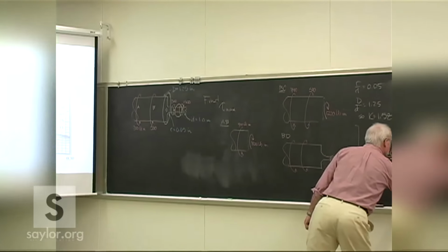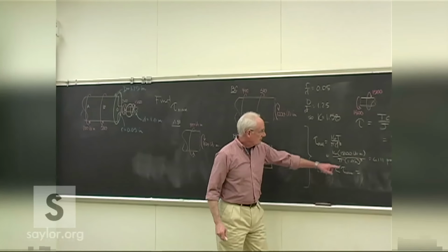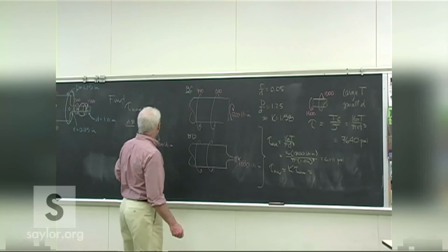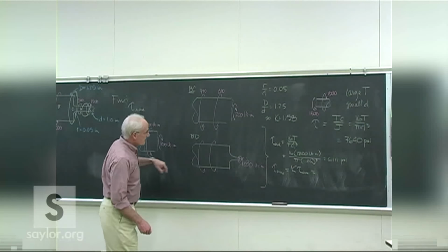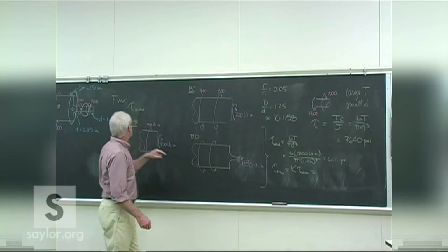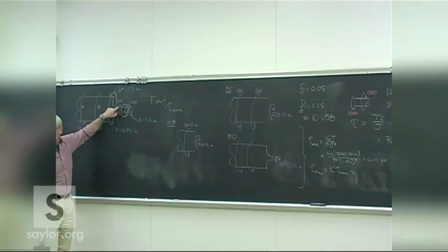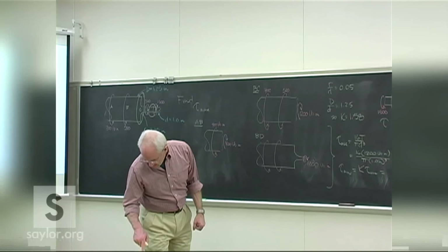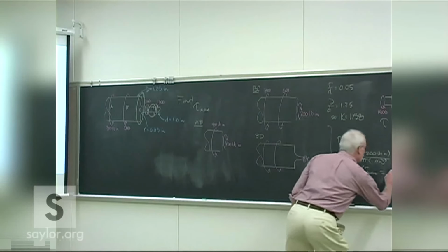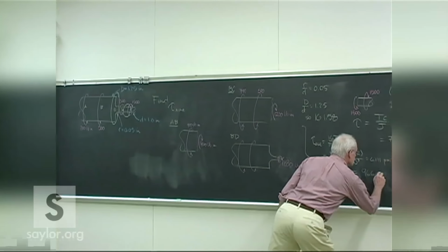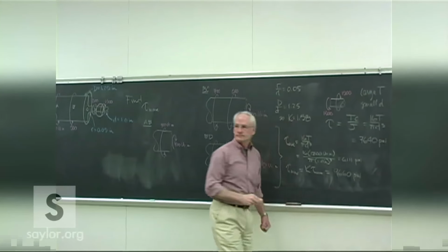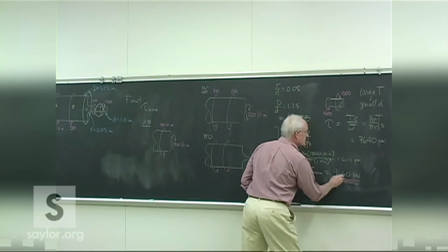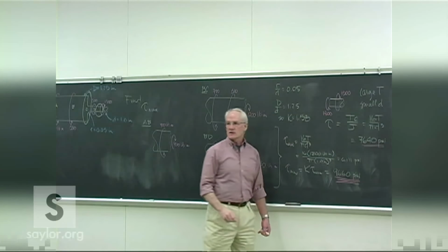Multiply the 1.58 times this. That's the average shear stress in the little piece before the 300 foot-pounds is added. So this comes out to be about 9660, which is quite a bit worse than the 7640.